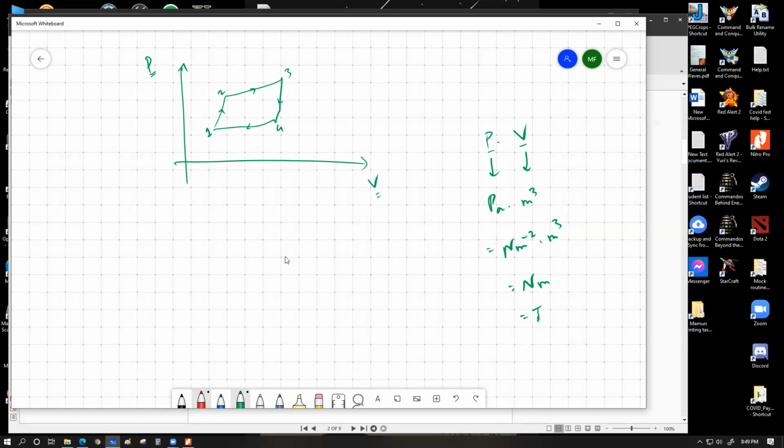So in this case, we can say that for the process of 1 to 2 and 2 to 3, we're going to have an increase of internal energy. In the process of 3 to 4 and 4 to 1, we're going to have a decrease of internal energy. So by finding the area under the PV graph, we can calculate how much energy change is happening to a certain system. However, for most of your syllabus, you don't have that process, because in many cases these things are not straight lines.